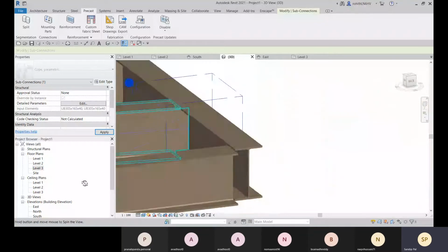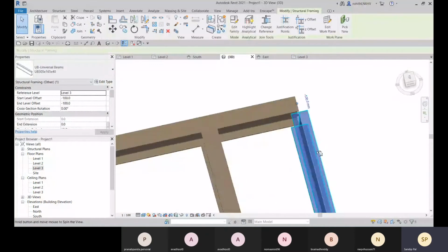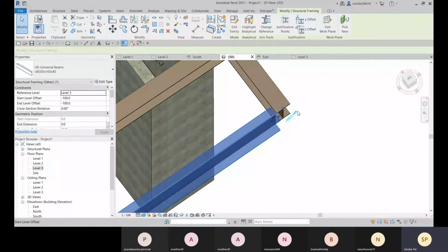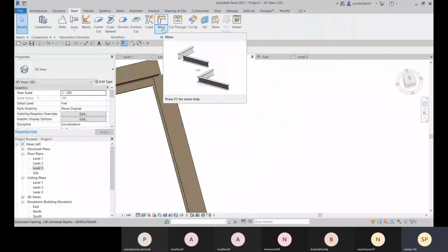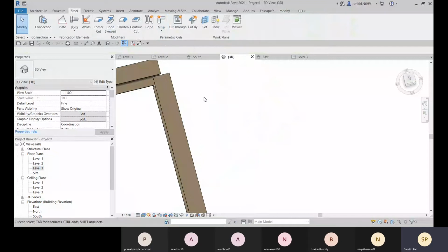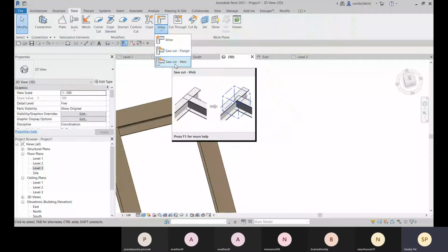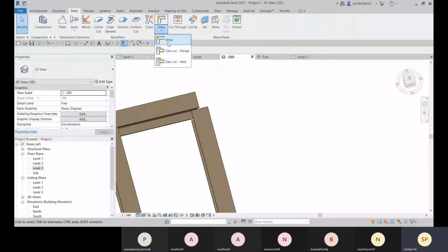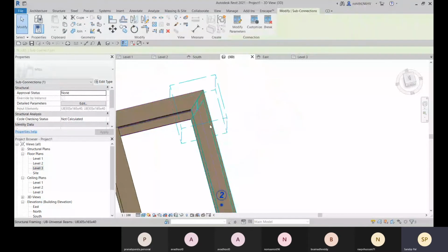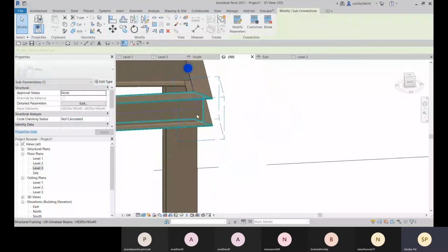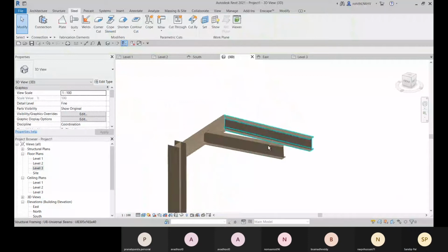Okay, so this way we can adjust it. All right. And for this, I can increase this. Okay. And then we have this corner joint or this cut. Okay. For the corners, I have this miter or saw cut web. All right. I have these options. Let me choose these two and let me press enter and this cut will be created. Okay, for the corner joint. All right.